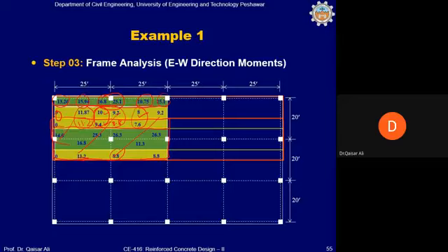These are the values, 14, and then 16.8, we have 26.3 and 28.3, we'll select 28, and 11.3 and 26. Now, if you compare the values of the interior frame column strip and the exterior frame column strip, they are very close: 14 and 13.25, 15.94 and 16.8, 26.8 and 26.3, 10.75 and 11.3, 25.1 and 26.3.